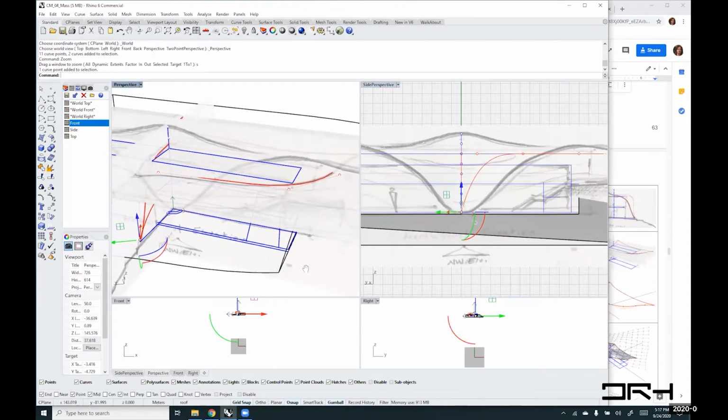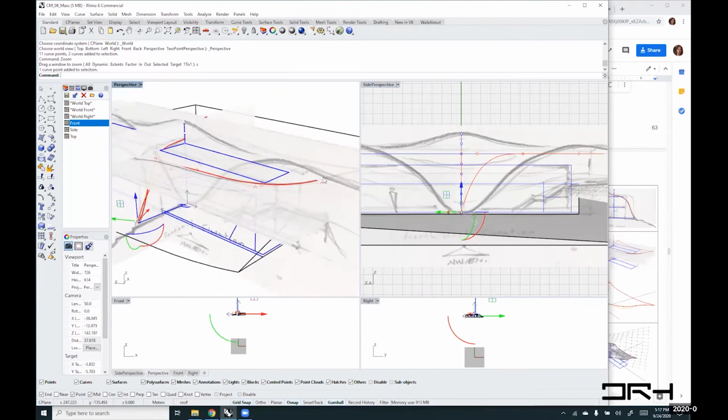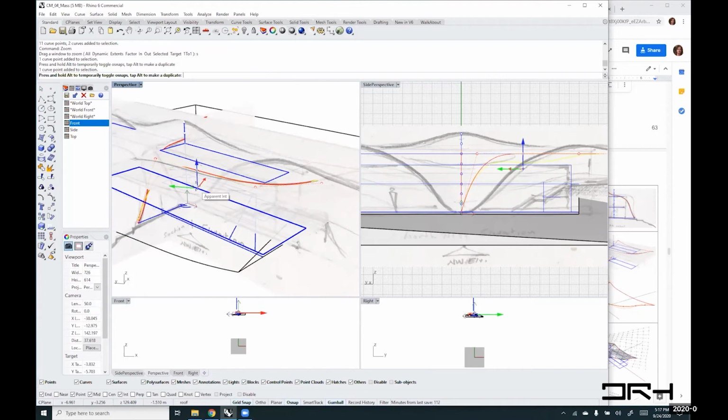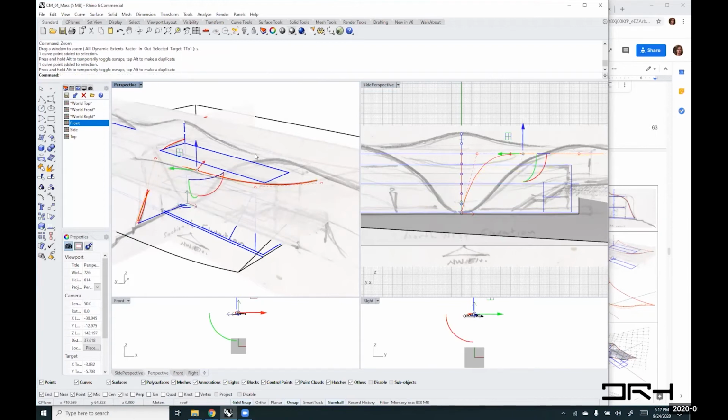So whichever view is easier for you to select from and reference, I will do the opposite here. In a perspective, I select the point and move it vertically. Escape. I'm not going to use any snap or grid snap here, and just move it freely down until I can see on the right view that it's actually starting to align more properly along the sketch that I have.